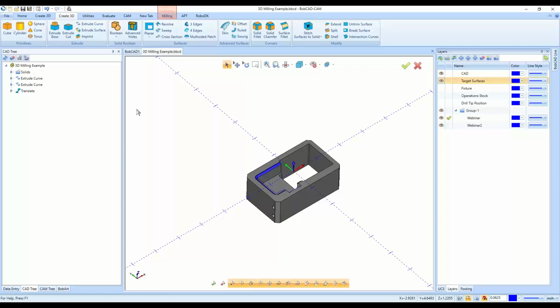Silhouette is a new 3D CAD function, very similar to section view, but you can extract more edges from surfaces to wireframe. With holes inside of a part and any other kind of cavities inside of a part, you can extract the wireframe in silhouette a little more easily than section view. Section view has to be right on, right in the area. We can go over that right now.